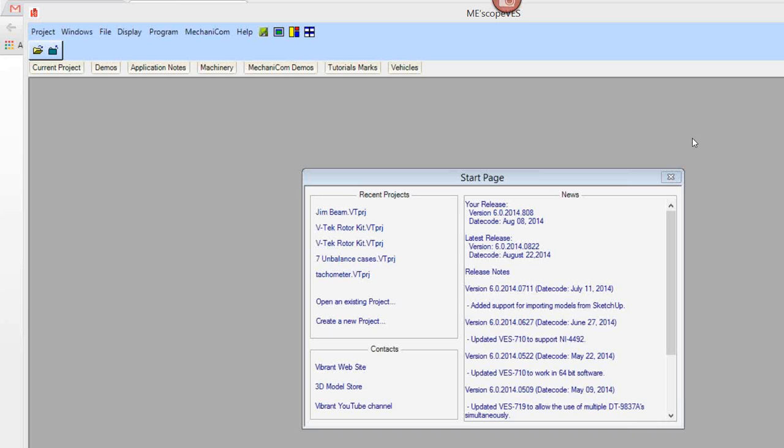I'm going to take you through an example here today where we're going to form cross-spectrum measurements between a number of accelerations and a reference accelerometer. Now, a reference is a fixed accelerometer location. And the reason we need a reference is so that we can get the phase between that accelerometer and any number of what we call roving accelerometers.